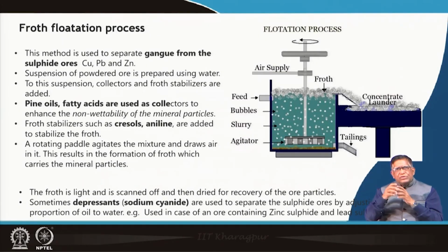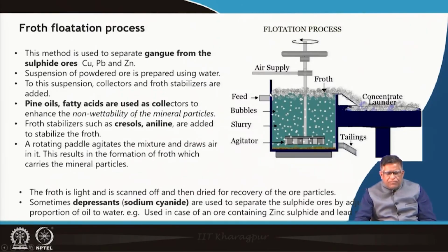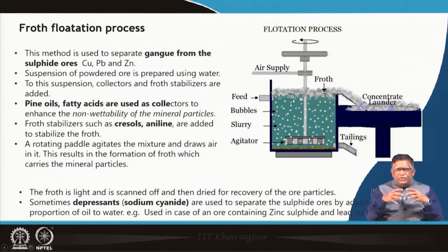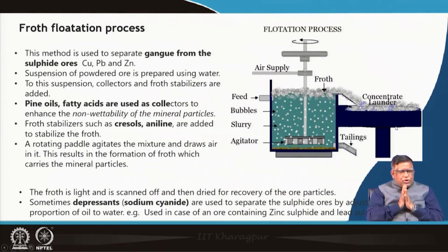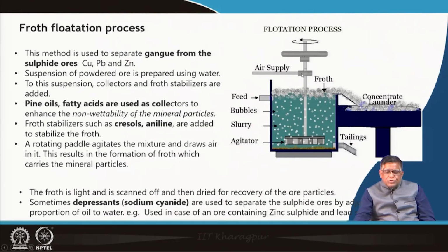And there are also sometimes some organic oils like cresols and aniline added to stabilize the froth, so that whatever foam is created at the top remains in the foam position and does not break. Because if the foam breaks, the particles that have been lifted inside it are lost. That froth is allowed to pass over here, so in this launder you get the concentrate.